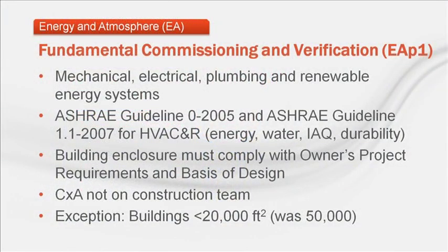From a commissioning standpoint, the normal systems must be covered. LEED v4 has also moved to industry publications as the basis for commissioning guidance. ASHRAE Guidelines 0 and 1.1 are to be used. In addition, for the first time, the building envelope or enclosure is covered by LEED. The prerequisite does not require envelope commissioning, but the commissioning agent needs to make sure it complies with the owner's project requirements and the basis of design.